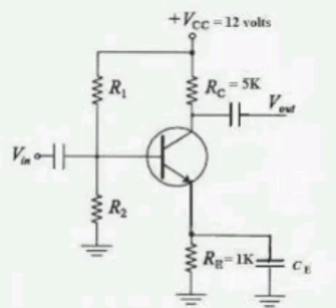Given circuit has voltage shunt feedback, IF equal to minus V naught by RF, that implies IF by V naught equal to beta F, that equal to minus 1 by RF equal to minus 1 by 4 kilo ohms. Draw circuit without feedback.